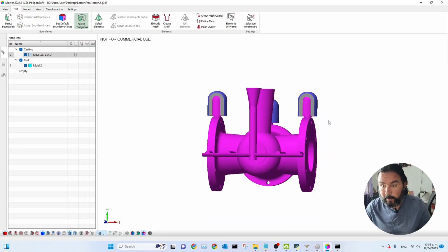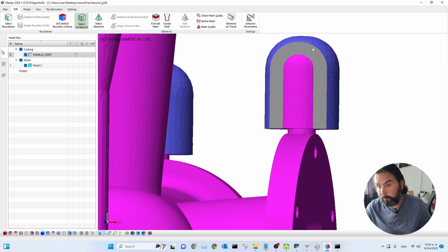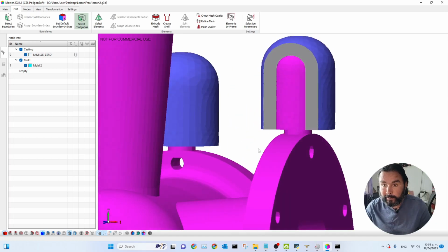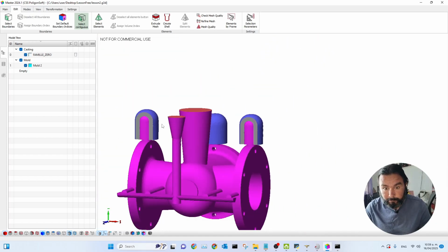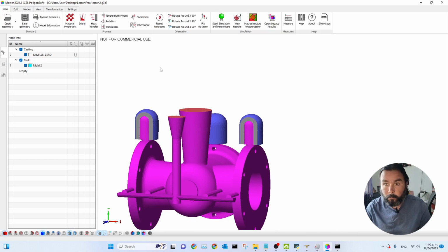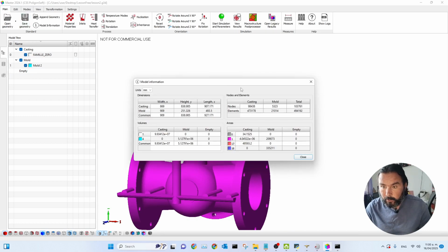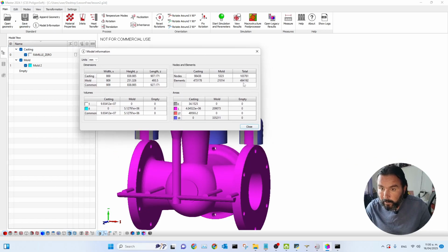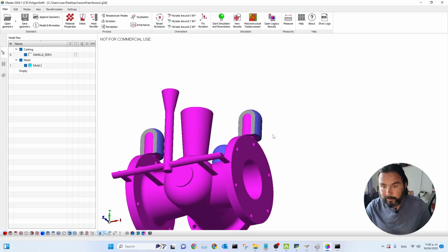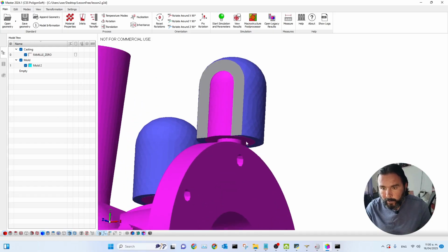As we can see, the program has created exothermic sleeves on the external part of our model. Just let me see, since we were very close to our mesh, I want to see how many triangles I have set. 494,000. I still have space to do the bottom part. Same as here, we select those surfaces.